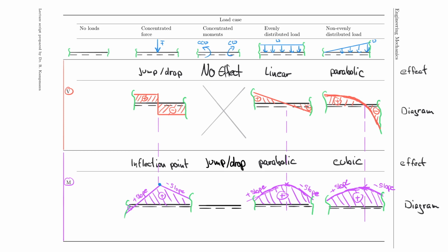It is actually the same way that the concentrated force behaves relative to the shear force diagram. We now have a concentrated moment impacting the bending moment diagram.